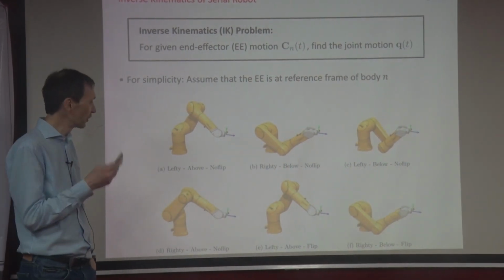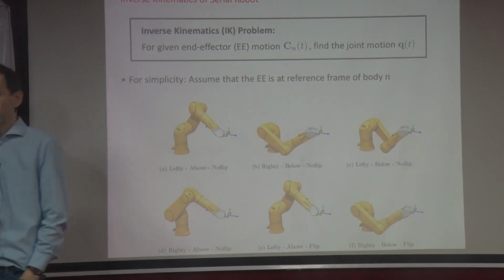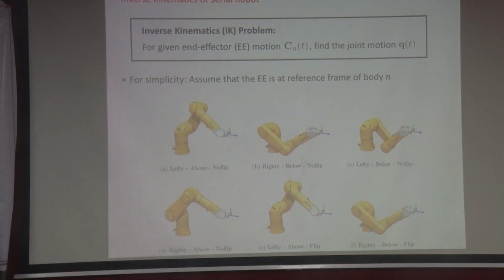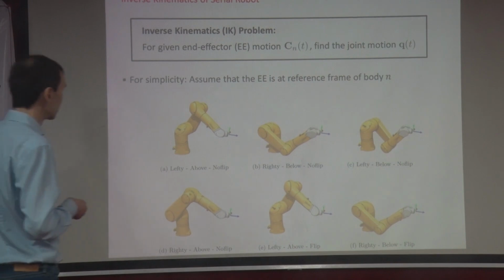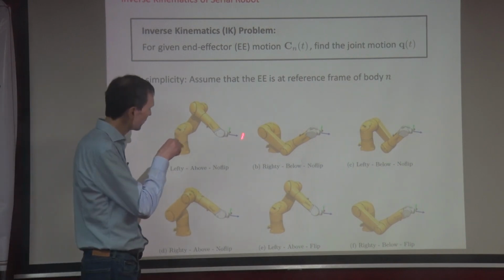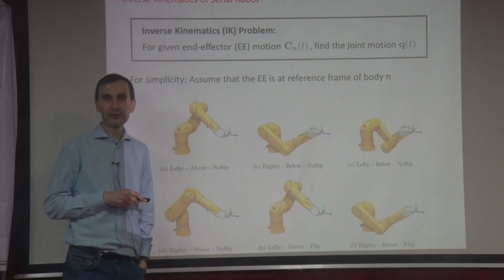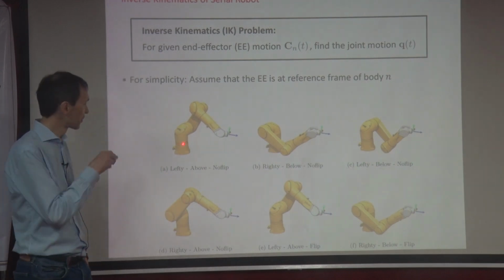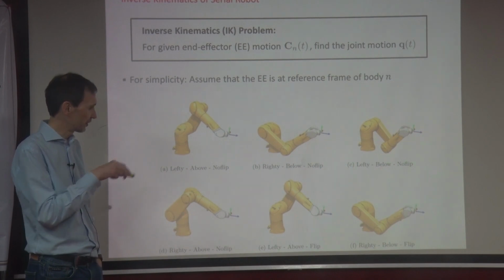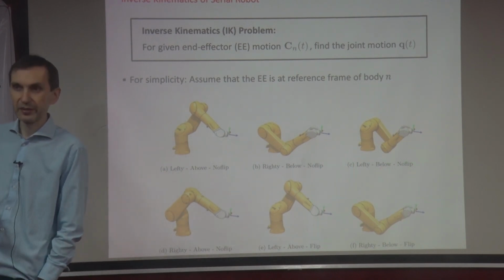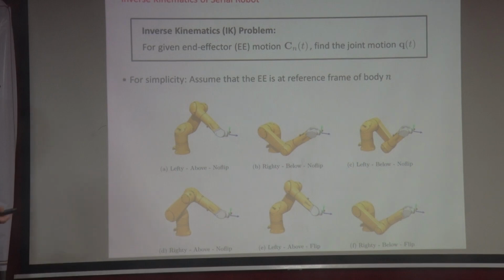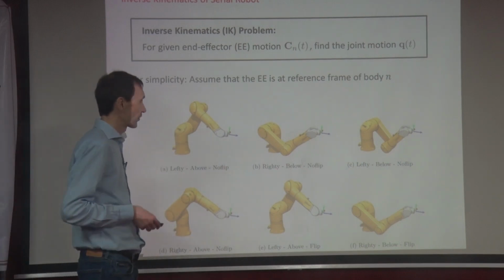The inverse kinematics is not unique. Not unique means I give you an end effector pose, you see it's all the same, but you get different inverse kinematic solutions for this. The joint angles are totally different, but they're all admissible. So which one do you like? Well, anyway, this is not a question.